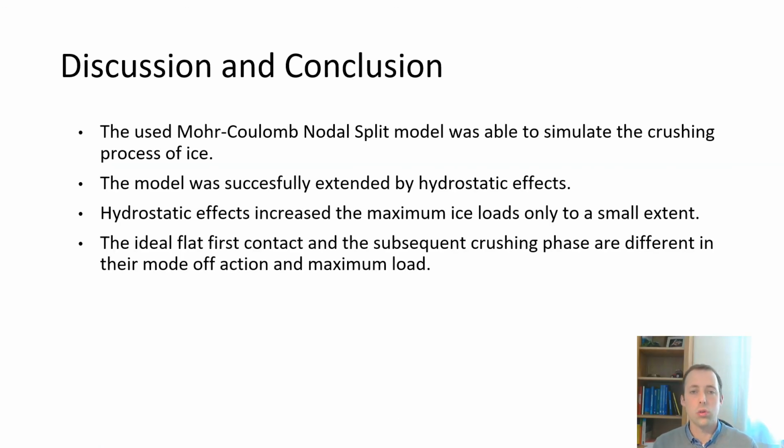So I would like to conclude my talk. The used Mohr-Coulomb Nodal Split model was able to simulate the crushing process. The model was successfully extended by hydrostatic effects. Hydrostatic effects increase the maximum ice loads only to a small extent, but they are very important to simulate realistic scenarios, so this rubble generation and so on.